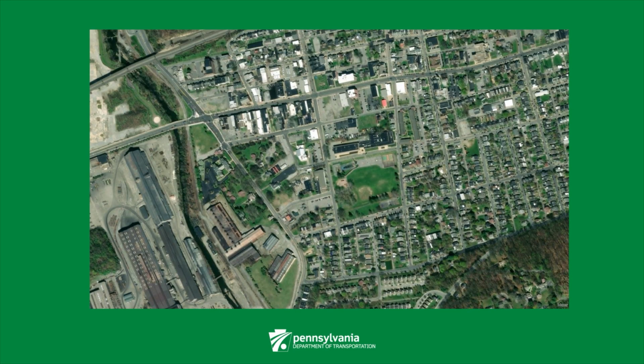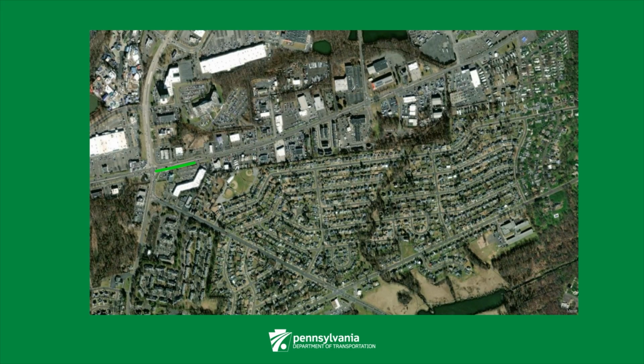Next, we have segments. For segments, PennDOT's roadway management system, or RMS segments, were used. These segments are generally similar enough from start to end that it is appropriate to analyze them as a single HSM segment. For multi-lane roads with secondary segments, the primary and secondary segments were combined to be a single HSM segment unless the roadway consisted of one-way streets.